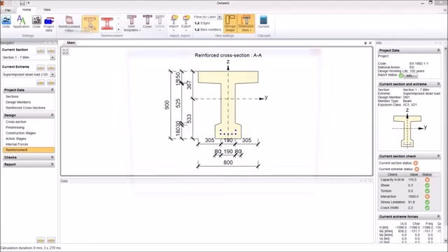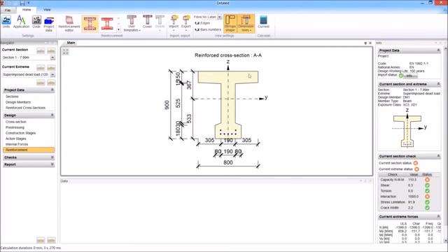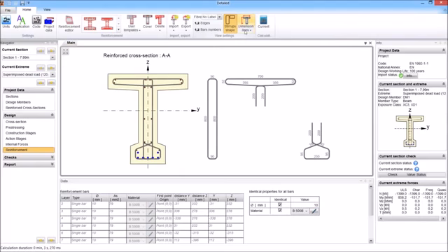And I use the template, and I will use 4 bars of 10 millimeters in the top, 0 bars at the bottom because I already have these strands, and 1 bar in the middle just to reinforce the reinforcing cage. Stirrups diameter 10 millimeters, 45 millimeters stirrups cover, stirrup distance 0.15 with the overlap 200 millimeters, and we will see. I will remove the dimensions.